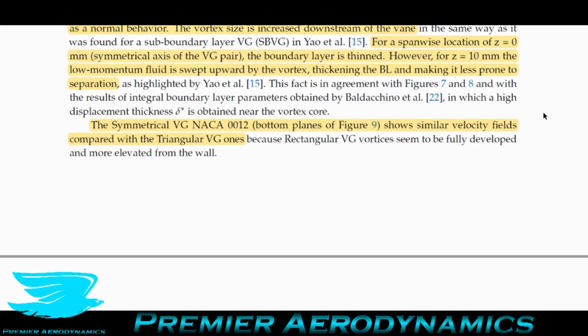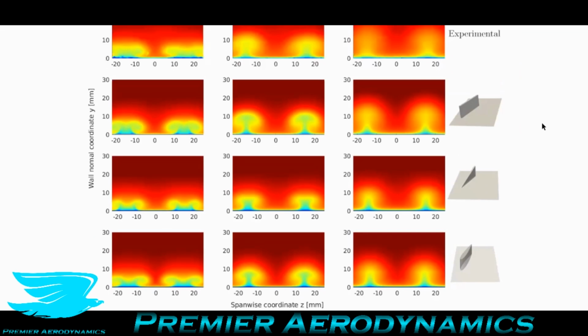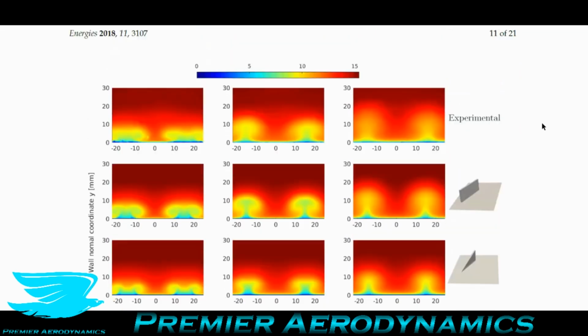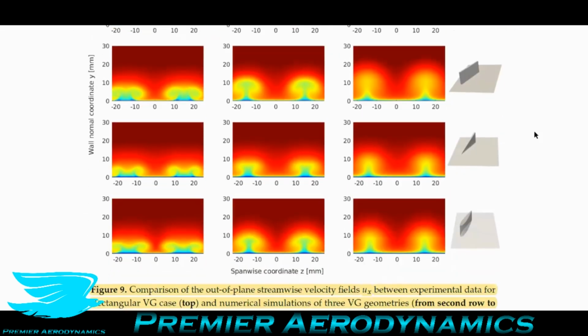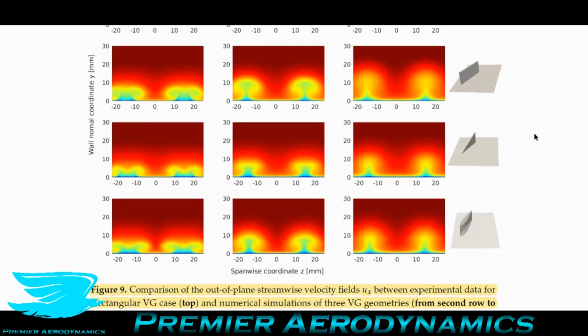You can literally come up with anything you want, and it will work. Now, one cool thing I have is the cross-sectional velocity planes as you go downstream of the different vortex generators. And it's really cool when you're very close to the vortex generator to begin with. You get typical roll-ups where you have two vortices of opposite signs rolling up.